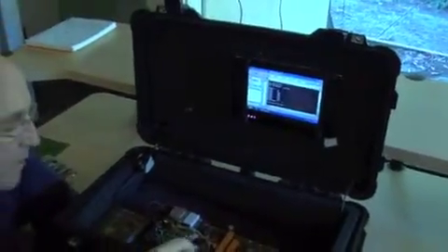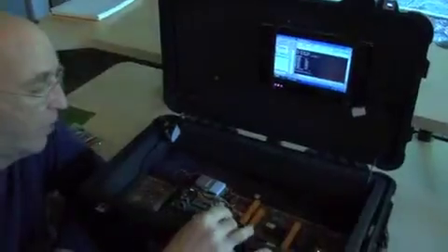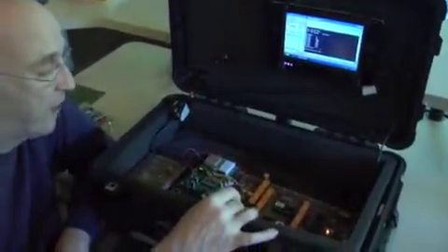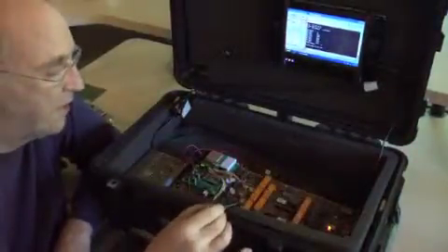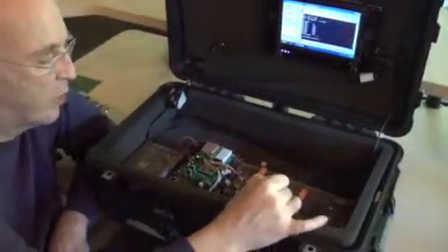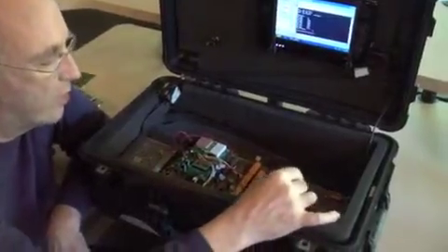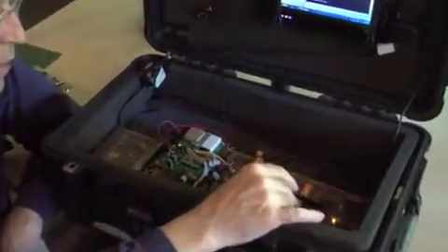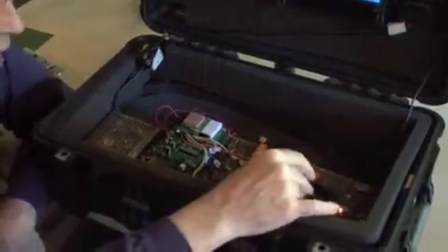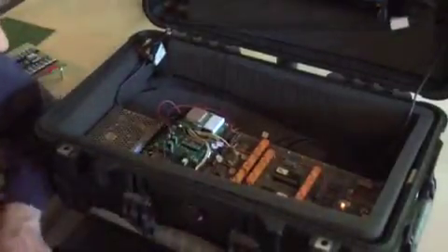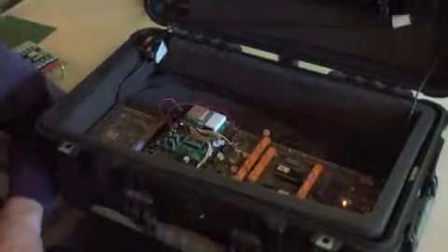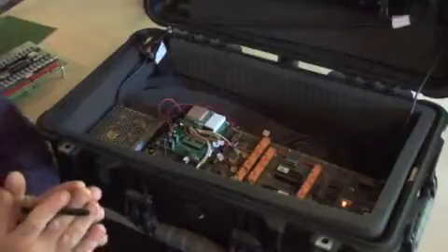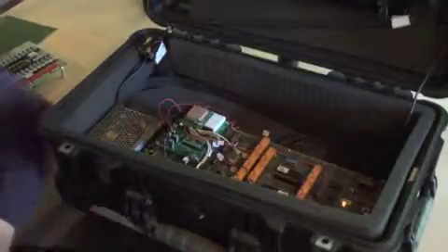Alright, so before I was interrupted by that cycling, I was going to tell you that these relays close in order to allow us to read the sensor as a regular memory device and do the comparison against the mirror memory. That is hardware compared over here via a 688 chip, and that signal goes back to the processor and tells whether there was a match between those addresses or not. There has to be a match in the data at those addresses.